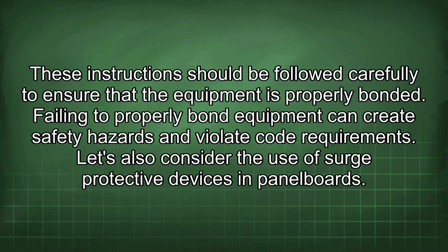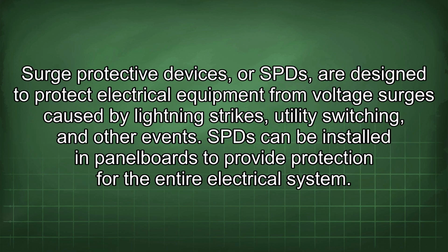Let's also consider the use of surge protective devices in panel boards. Surge protective devices, or SPDs, are designed to protect electrical equipment from voltage surges caused by lightning strikes, utility switching, and other events. SPDs can be installed in panel boards to provide protection for the entire electrical system.